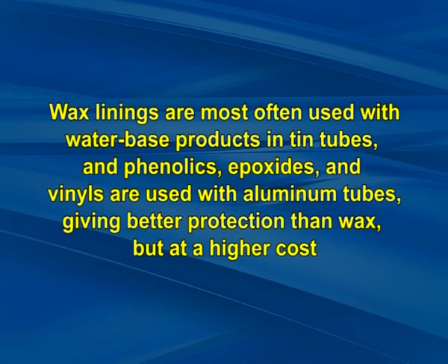Wax linings are most often used with water-based products and tin tubes and phenolics. Epoxides and vinyls are used with aluminum tubes, giving better protection than wax but at a higher cost. When acidic products are packed, phenolics are used, and for alkaline products, epoxides are used.